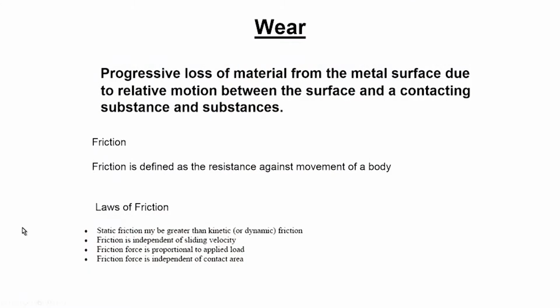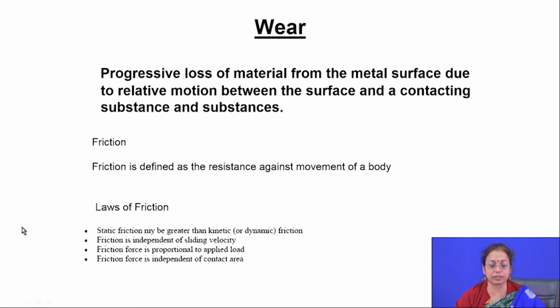So, if you quickly go through wear, it is basically the surface-dependent failure of a component, and you can define it in this fashion: it is the progressive loss of material from the surface due to relative motion between the surface and a contacting substance or substances.